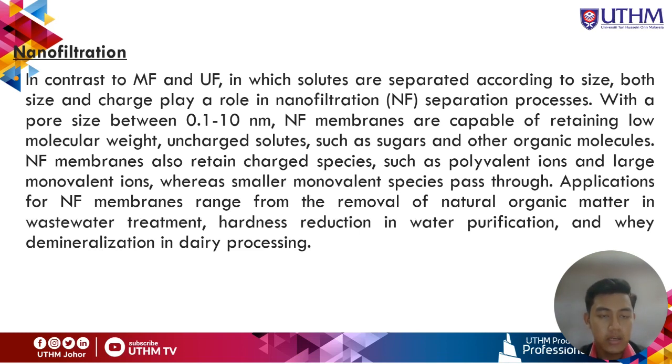Nanofiltration membranes also retain charged species, such as polyvalent ions and large monovalent ions, while smaller monovalent species pass through. Applications for nanofiltration membranes range from the removal of natural organic matter in wastewater treatment, hardness reduction in water purification, and whey demineralization in dairy processing.